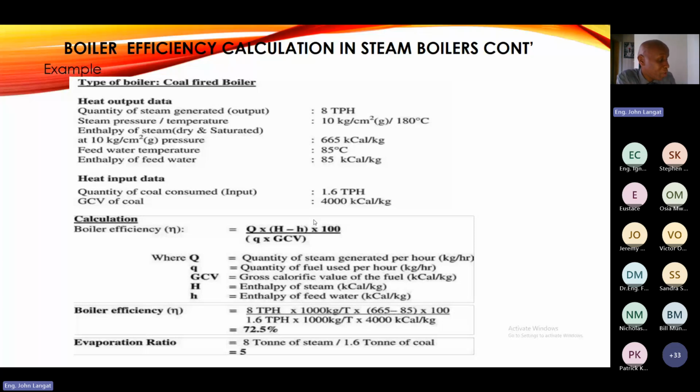And that's what I was saying. At the end, if you are coming to calculate the efficiency on this screen here, you will have to calculate how many kilograms of firewood you used in order to calculate the gross calorific value. Because calorific value is given in kilocalories per kilogram. You're not given per meter cube. That's why they have to interpret it. Of course, the main primary reason why they are using cubes is because it's always stocked in cubes at the firewood shed. So they have to issue it as cubes. But the weighing, when they're converting it to kg, is for calculating the efficiency.